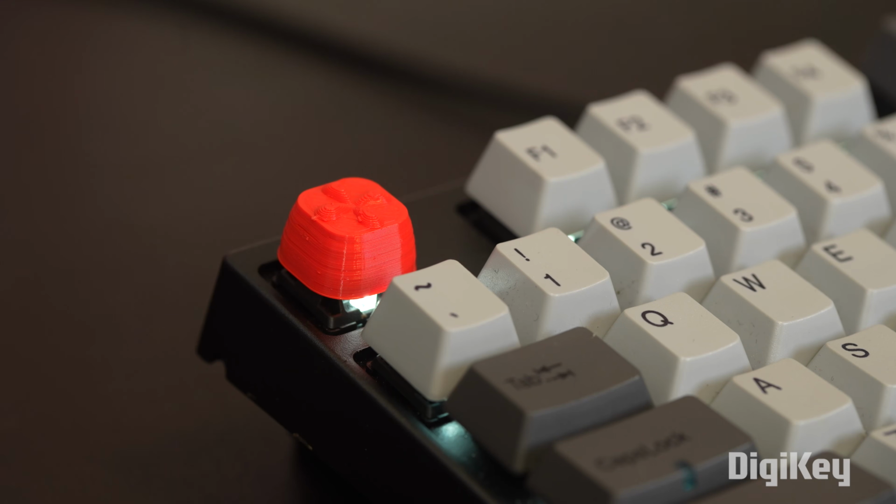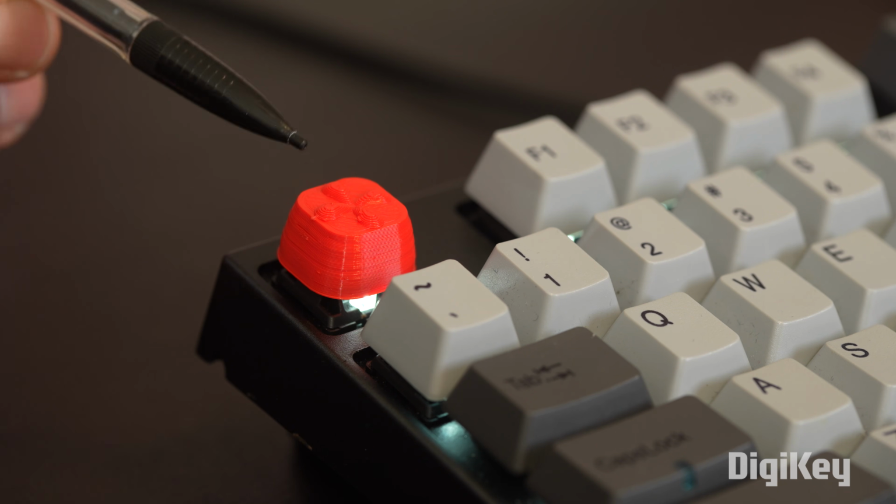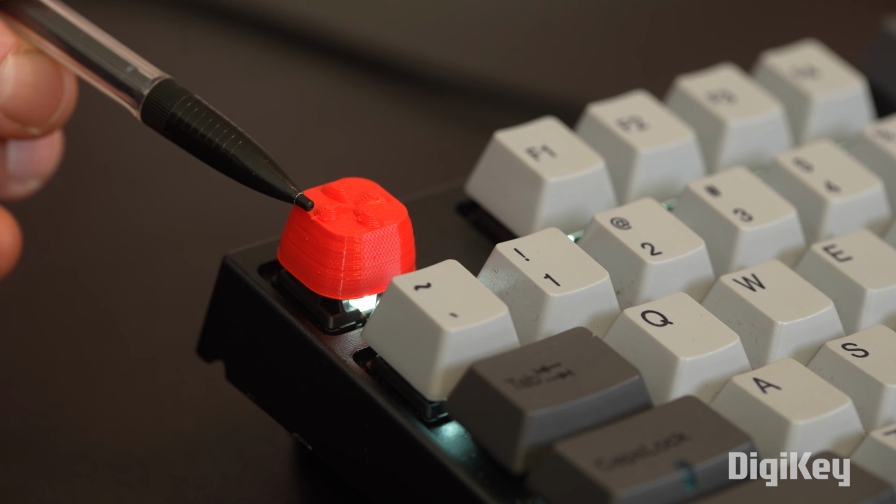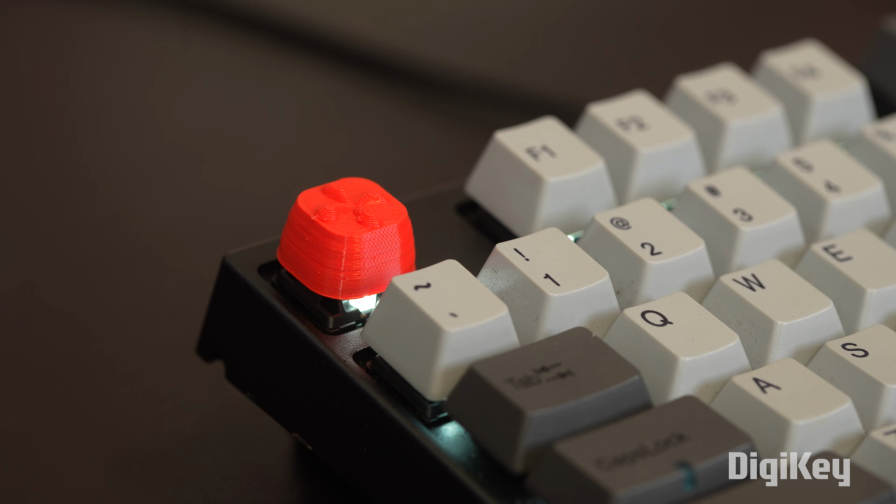I'll show you how to make this custom keycap for a mechanical keyboard. We'll need to use pipes to make the rounded surface, and we'll use lofts to design the top. Along the way, I'll show you how to use the revolve and subtractive pipe tools.